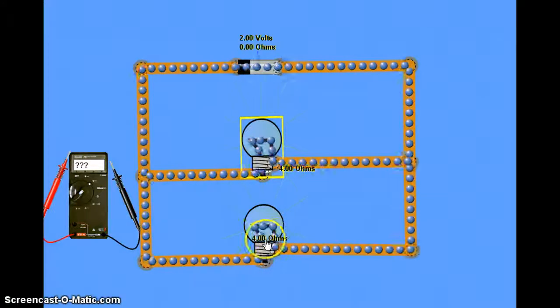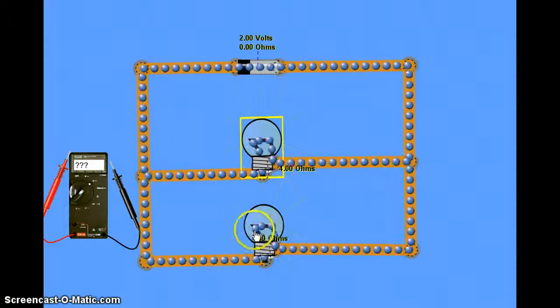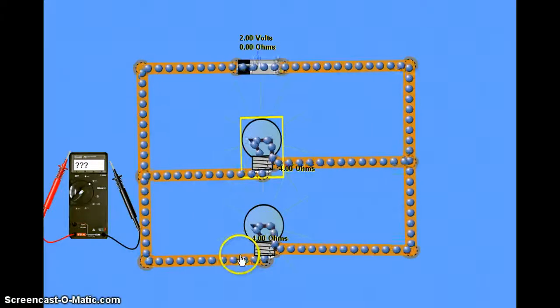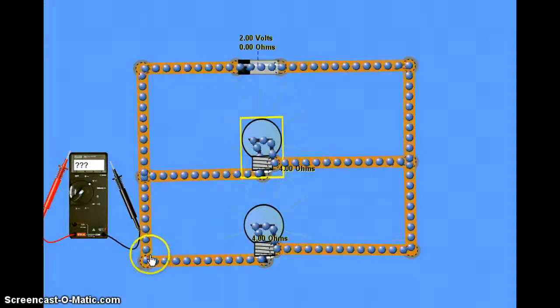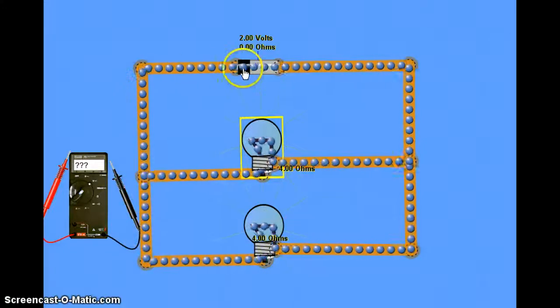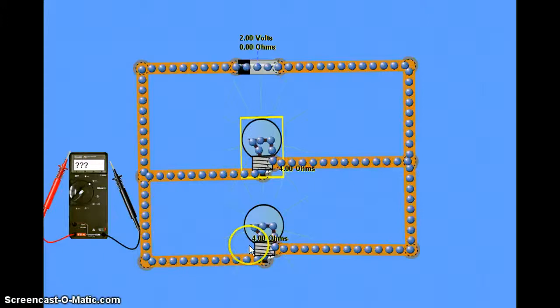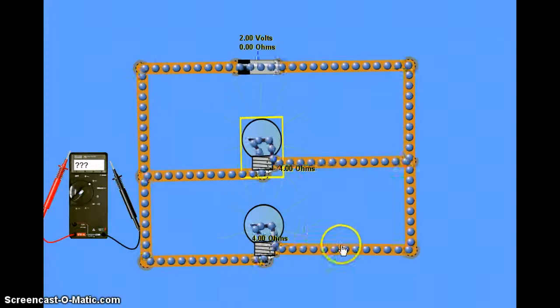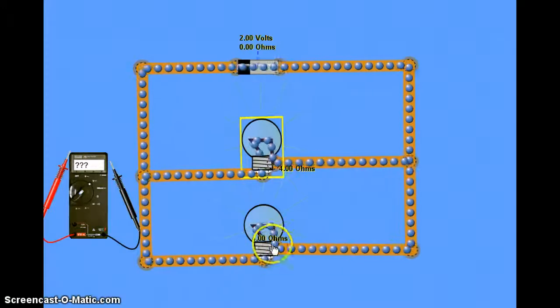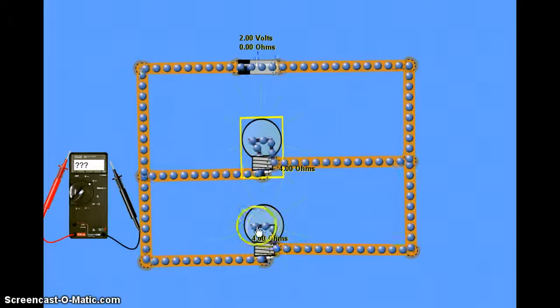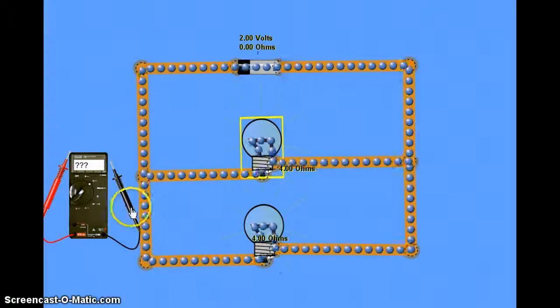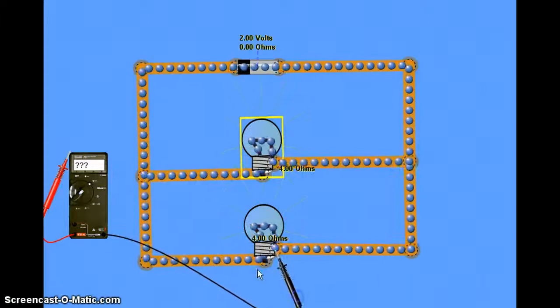If it goes through this resistor, in our analogy through this obstacle course, it would use up both monster drinks, because after it's been through this resistor, it's then going to go along here, back up there, and back to the battery. So it's not going to go through any more resistors. And so any charge coming along here would still have the full 2 volts, each coulomb, 2 joules of energy, and it would use it all up in this resistor. And so if we put our voltmeter over this resistor, we'll notice that it reads 2 volts.